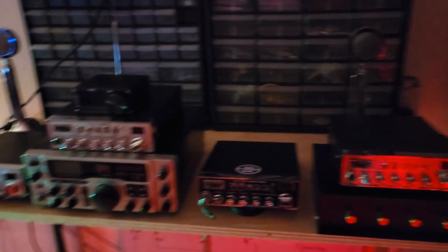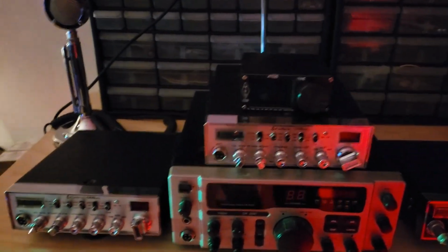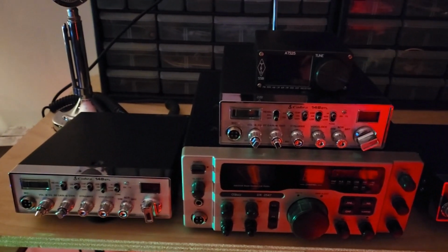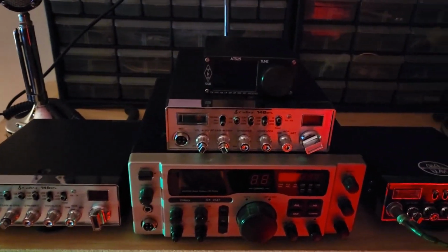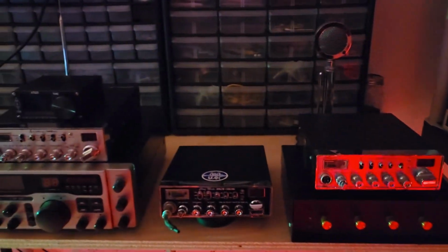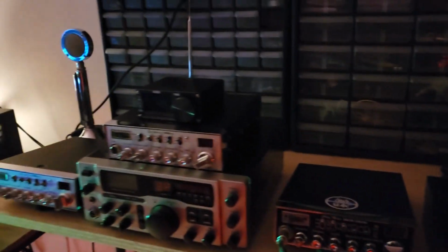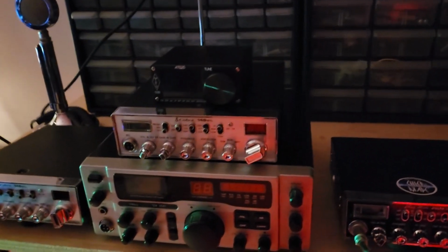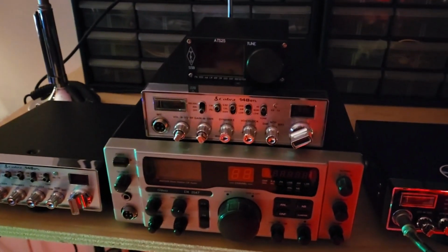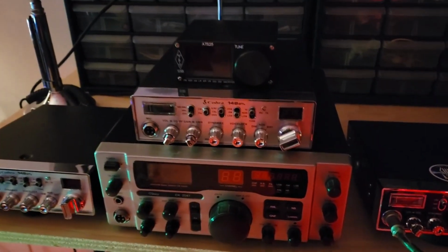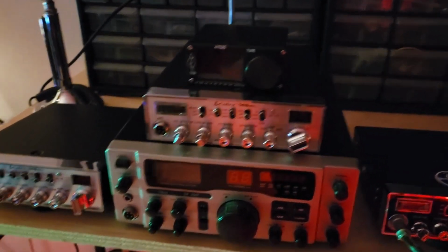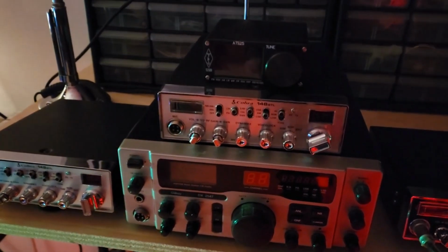So it depends what time of day, just like the ham bands. Sometimes you can roll those filters open wide, and when it gets really busy, you narrow them in. It has its uses, when you know when to use it. But you need to control it. You have to have filters. On my transmitter, I have my band pass filter. On something like that modulator, you might have to do that in the audio portion to narrow it down to 5 kc if you want to keep it all on the channel. In fact, you might have to roll it in even a little bit narrower, maybe like 4.6 kc, because it's going to roll off. By the time it rolls off, you might bump into the other channel. It's something to be aware of.